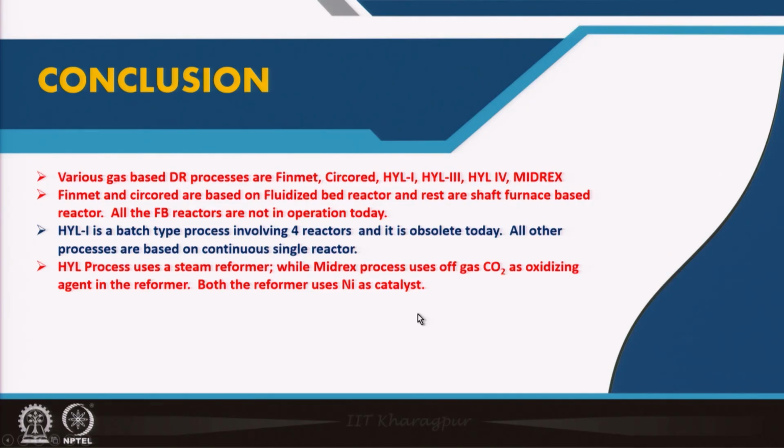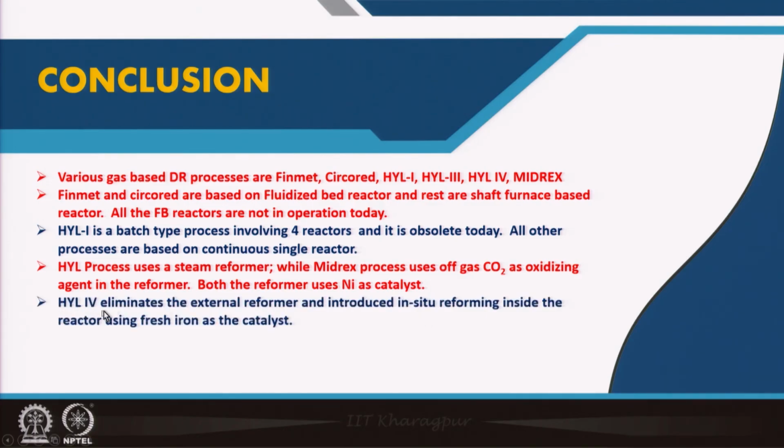And the HYL4 eliminates the external reformer and introduced in situ reforming inside the reactor using the fresh iron as the catalyst. This is a very unique development, because if you do this in situ reforming, the catalyst problem is gone totally.